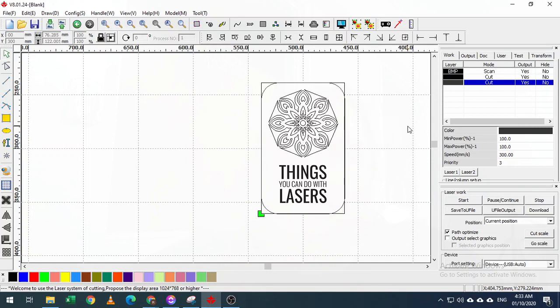One thing to consider, even if your laser output is rather high, is that if you don't give enough time for the laser to actually cut through your material, it won't cut the material and will rather leave a mark, which is something that you could use if you want to put some style in your fabrication. The same thing with scanning.